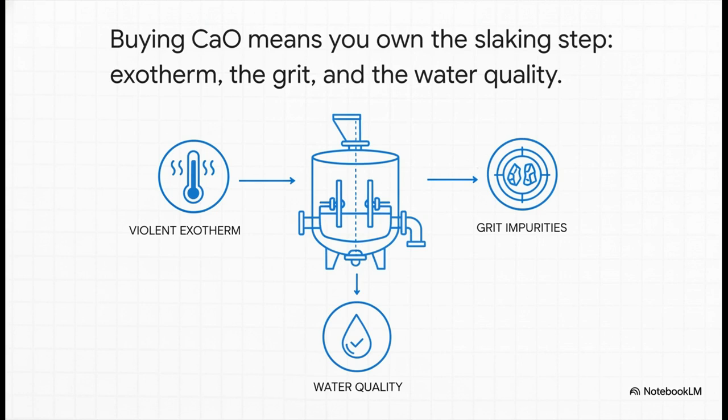You also need really good process water. Slaking with hard or sulfate-rich water right on site produces a visibly poorer hydrate. So if you don't have the heavy equipment to slake it safely, you really have to buy hydrated lime, regardless of that freight premium.